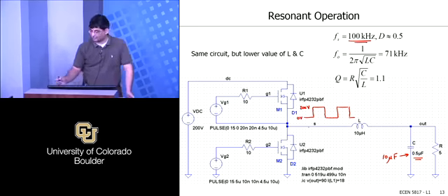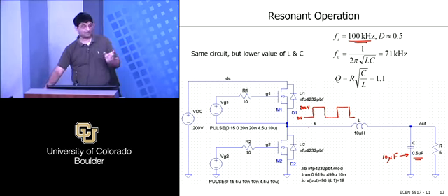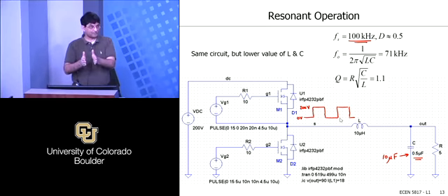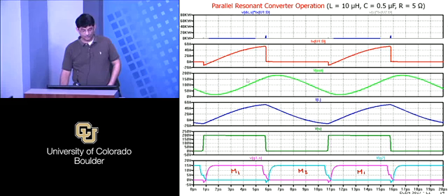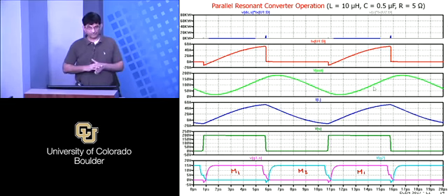And if you put it in a resonant tank which has a resonance frequency close to the switching frequency, well, it's going to keep that fundamental, it's going to attenuate away the higher harmonics, so it's going to basically take the square wave and keep its fundamental, smooth it out, essentially. And that's what you're seeing, right? Basically a smoothed out version of that square wave, but the average value is still 100 volts, right? Makes sense.